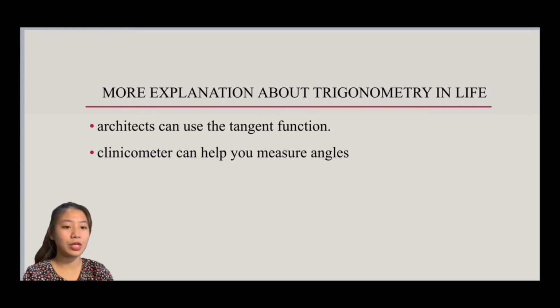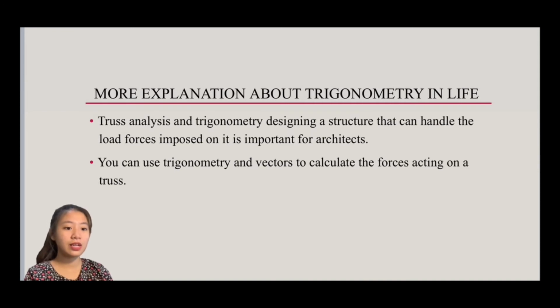Clinometer can help you measure these angles. This is an older device, but the newer one uses digital technology to give more accurate readings. You can also calculate the distance of the structure if you know the clinometer angle and the height of a structure. Next, truss analysis and trigonometry.